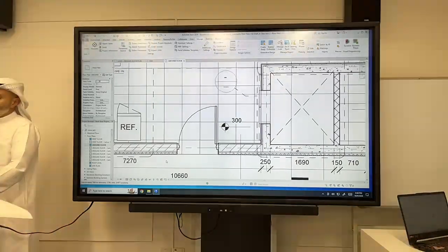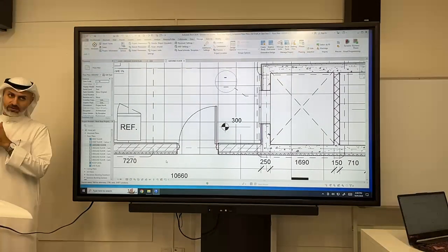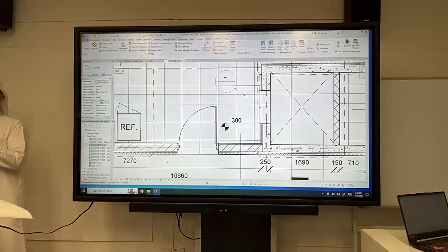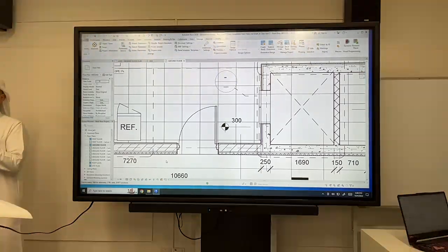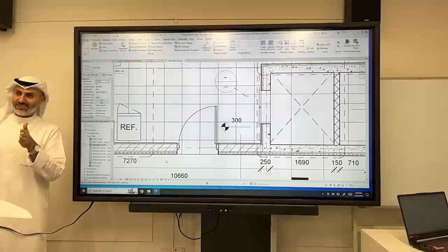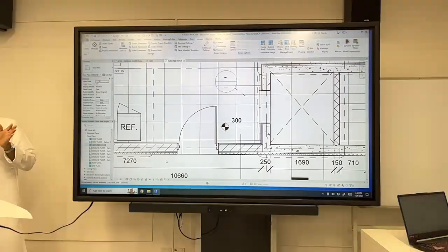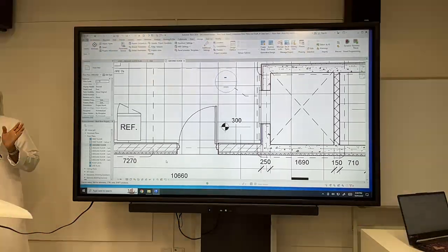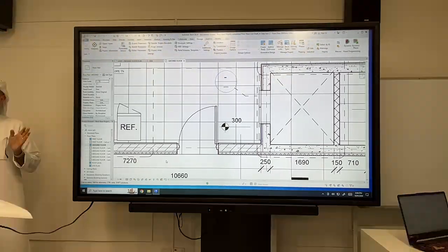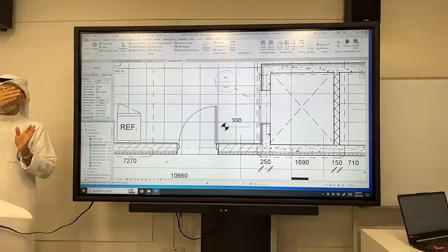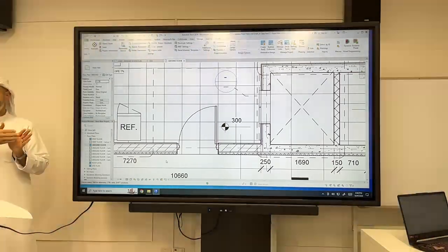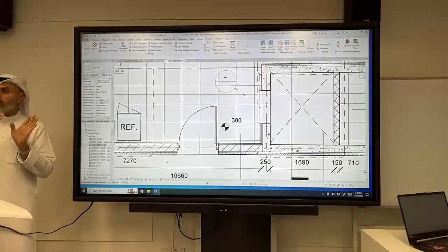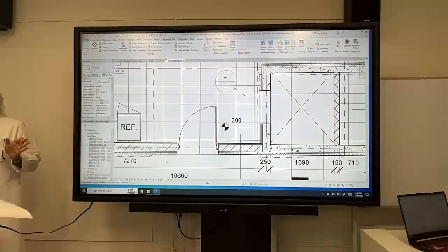Now, remember we talked about when to use white brick and when to use black brick? Which one is more expensive, the white or the black? The white is more expensive. Okay, it's more expensive, it's lighter, it's an insulating material. But we don't use it everywhere. We only use it with exterior, and we cannot use it when we have stone. So stone, like marble or travertine, because of the nails or the mechanical system, you cannot use the white one. It's not strong enough to hold the material.